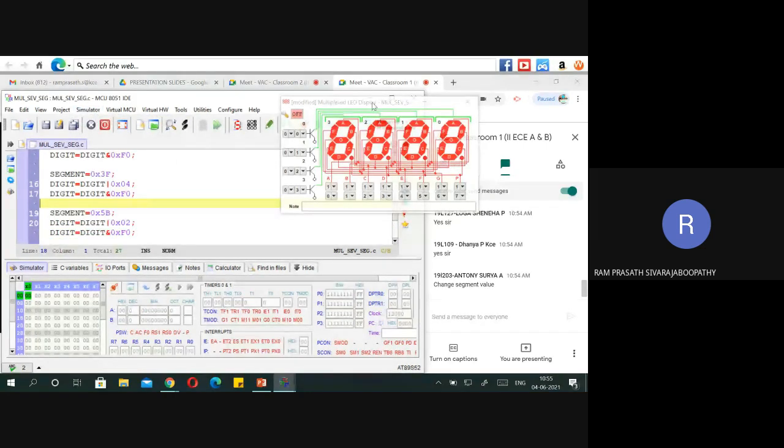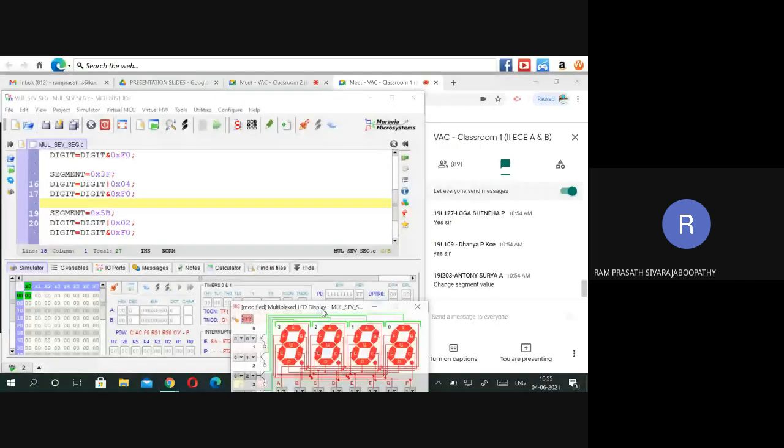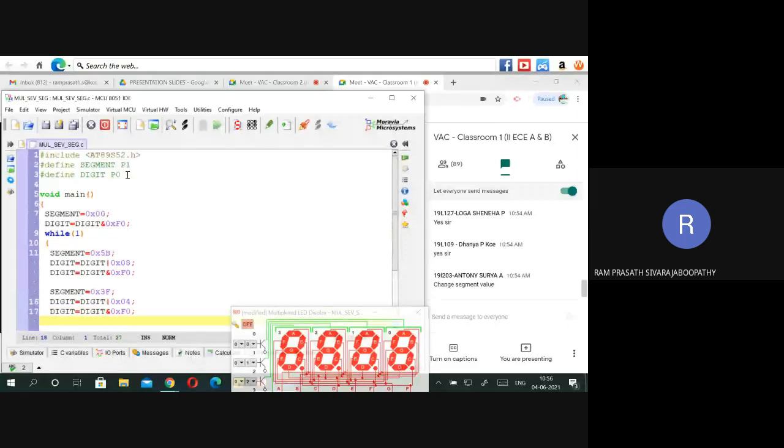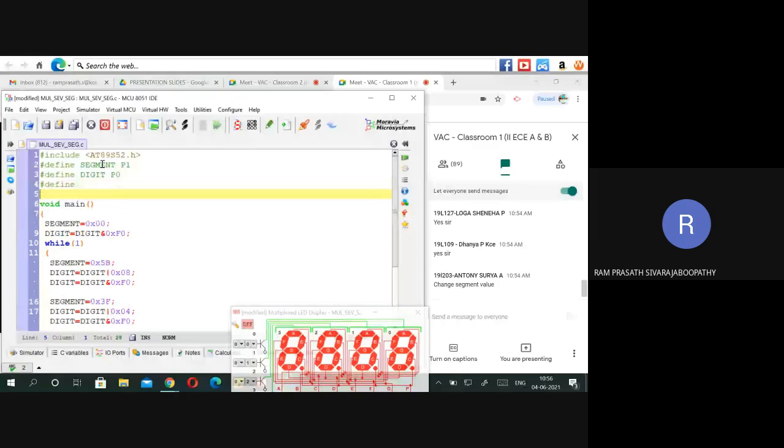Okay, fine. So kindly people help me to find the 7-segment code for all the numbers. Please type 0 to 9 in the chat. Meanwhile, I will tell you how to do this in a loop. Fine. So initially, I should have a pattern. Like the scanning, what we done in matrix keypad. Here also we are going to have a thing called pattern. So the initial pattern is going to be 0x80. Why it is 0x80?